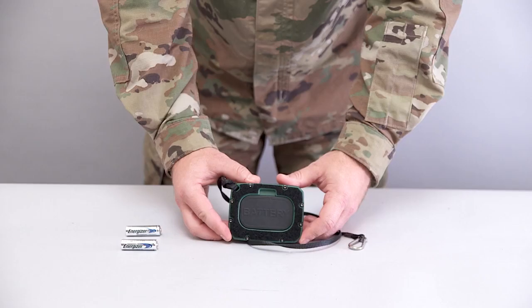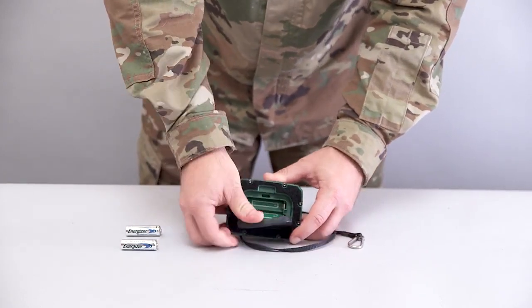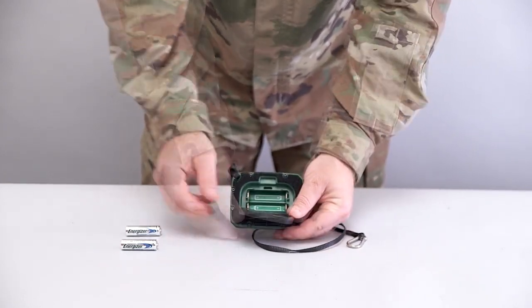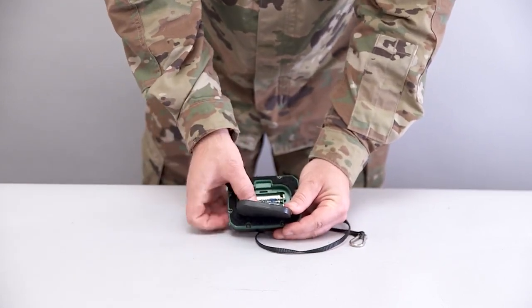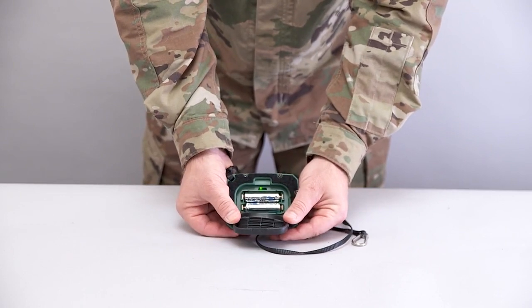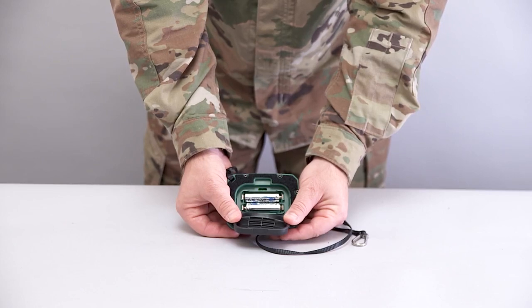CKM with the SIM. To power on the CKM, conduct the following. Open the battery compartment on the back of the CKM. Insert two lithium 1.5-volt AA batteries. Ensure the polarity matches the diagram in the battery compartment. The CKM LED will briefly flash green, then red. Then it will flash green twice per second, indicating that it is ready to receive the configuration code. Observe the device BIT passes.